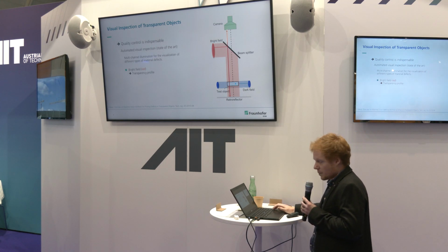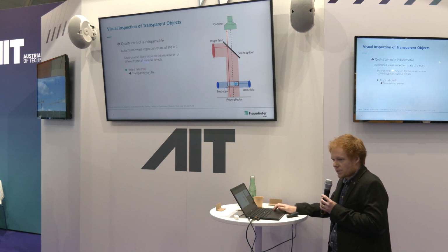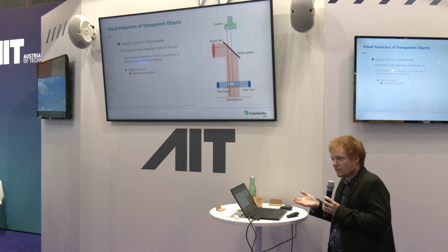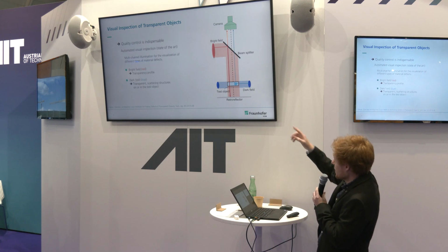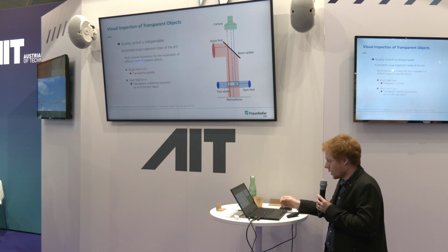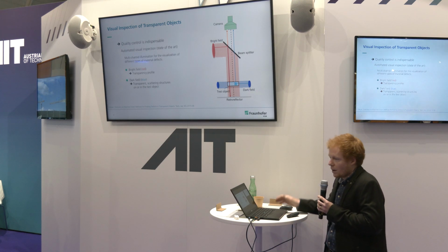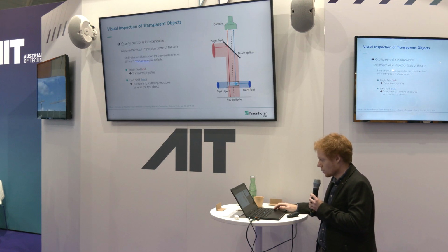And to find scattering particles, we illuminate the object from the side with the assumption that in the case of no defect present, no light reaches the camera, and if we have something scattering like this air bubble here, some light will be scattered into the camera and we can make this defect visible. For such simple objects, the problem is already solved. You can buy existing solutions.